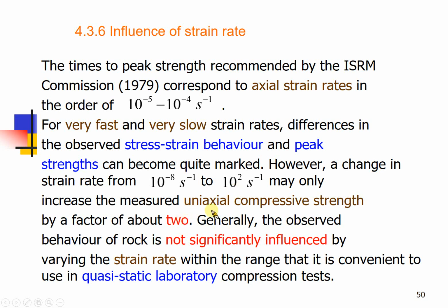The uniaxial compressive strength could grow up to twice that of the slow one. Usually, if you have a faster loading rate, you will derive stronger results. But within this range, it is okay and not influenced too much.